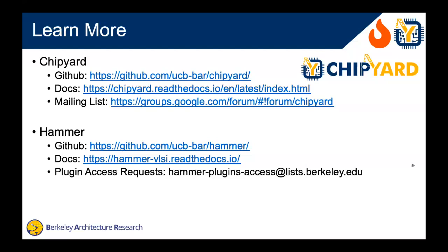So the power bit, do you guys have a power switch plug-in? And also, do you already have low power features, like isolation? So we have some UPF, CPF stuff, but we don't support isolation cells yet. We don't have that as a feature yet. But we do have level shifters and things like that.